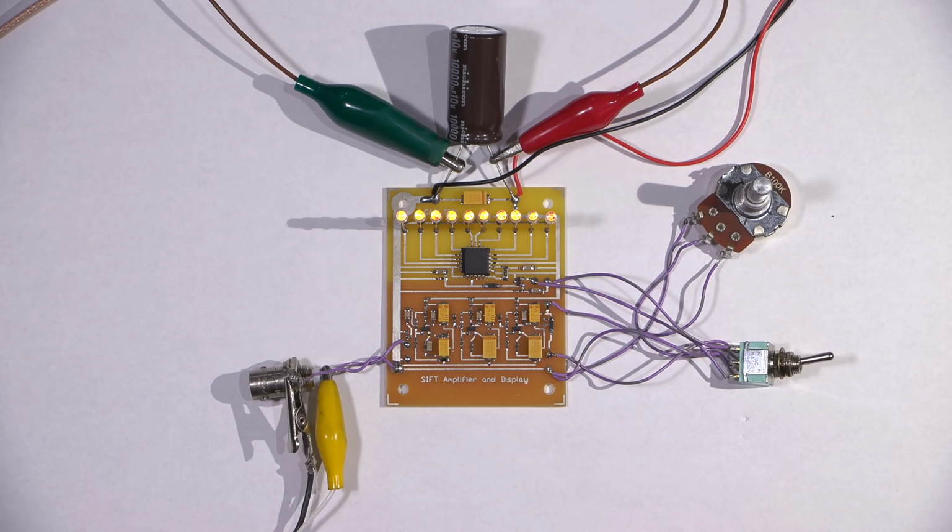So I could probably use just a little bit more amplitude. You know what that probably is? This is a Wien bridge oscillator inside the audio generator that I'm using, and there's probably temperature variation going on in it. That's how incredibly sensitive this thing is right now, right? Because the amplitude is so incredibly low. If I give it just a touch more amplitude, I'll probably be able to keep that last LED on.